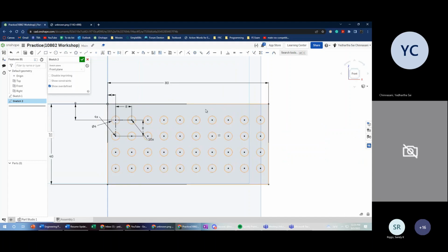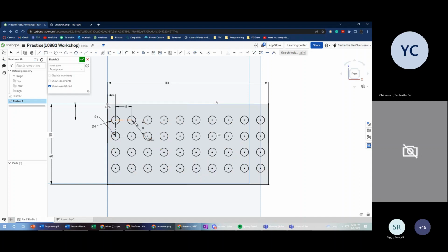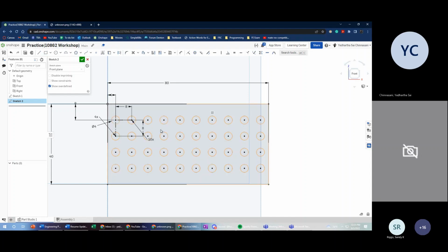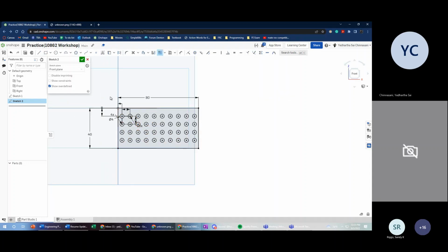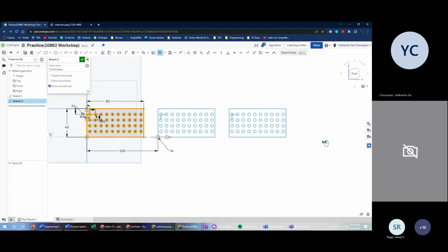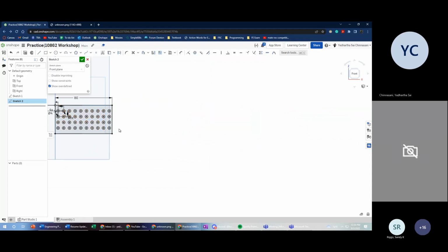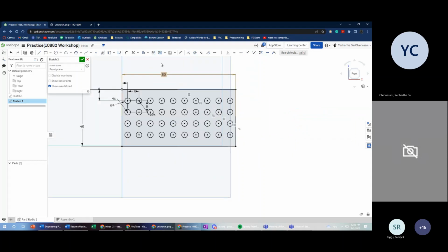And this is something that we use a lot because in FTC, you would like to leave as many holes as possible. I use it basically in almost every sketch I make, because it's just easier than drawing multiple different circles at one time. And you can do this with circles, you can do it with any entities. So I could pick this entire thing and linear sketch pattern it across. I could just do 100 millimeters and you'll have 4 of the same circles. So that's a tool I use a lot.